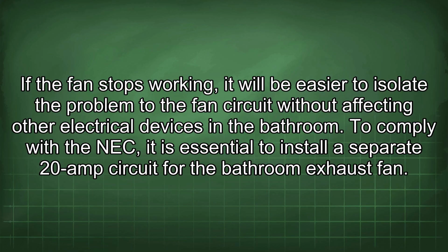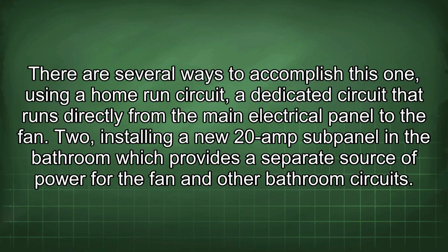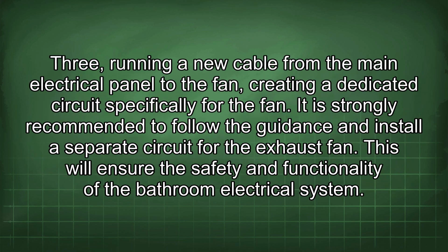To comply with the NEC, it is essential to install a separate 20-amp circuit for the bathroom exhaust fan. There are several ways to accomplish this. 1. Using a home run circuit, a dedicated circuit that runs directly from the main electrical panel to the fan. 2. Installing a new 20-amp sub-panel in the bathroom which provides a separate source of power for the fan and other bathroom circuits. 3. Running a new cable from the main electrical panel to the fan, creating a dedicated circuit